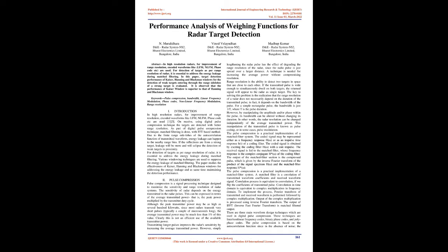duty cycle. Although the peak transmitter power may be as high as several hundred kilowatts, since most radars transmit very short pulses, typically a couple of microseconds long, the average transmitted power may be much less than 1% of this value. Clearly, this is not an efficient use of the available transmitter power.